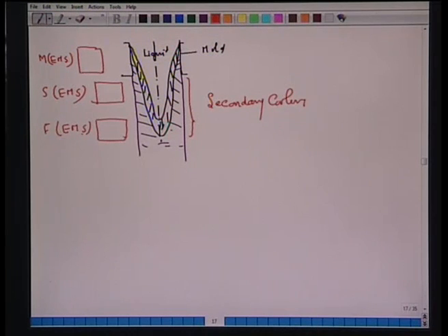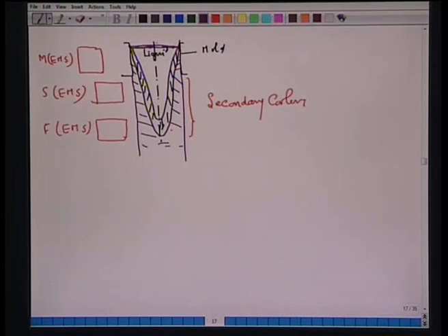Now you have to think also how you are going to install, because when the liquid steel enters into the mold, there is also a liquid flux here. The mold is water cooled, so all types of gadgets are there. There is a gadget of water cooling, there is a gadget of mold steel level control, there is a gadget of constant supply of the flux, and into that environment an electromagnetic stirrer has to be installed.